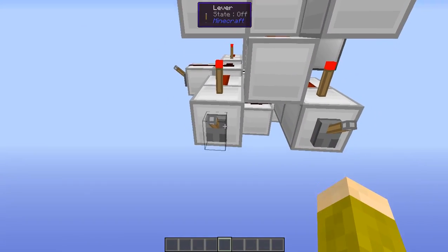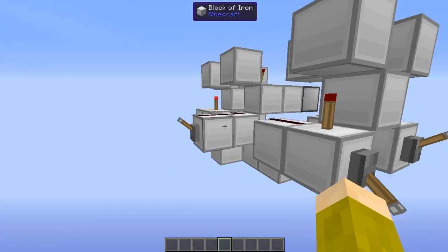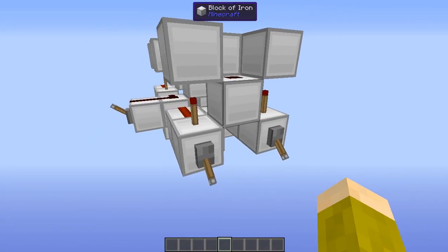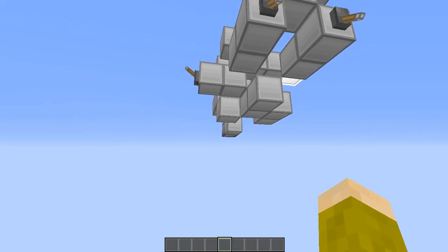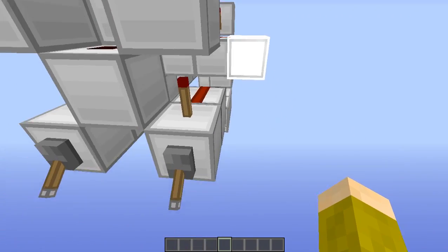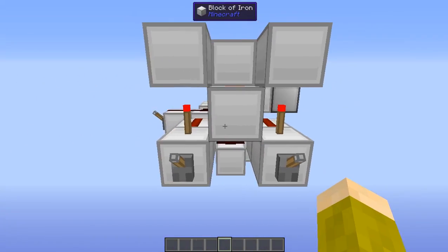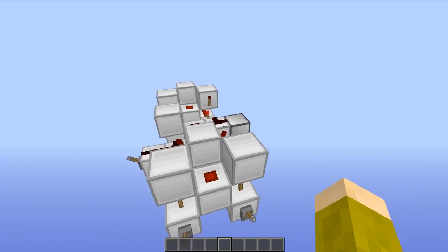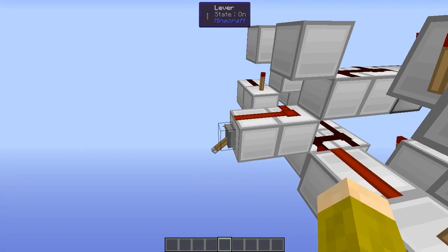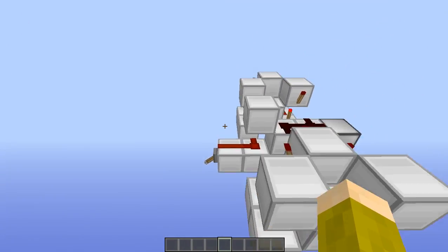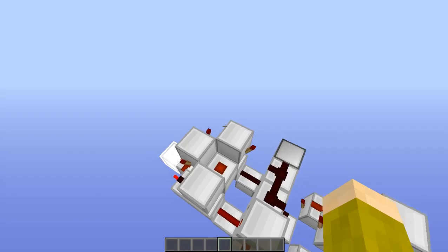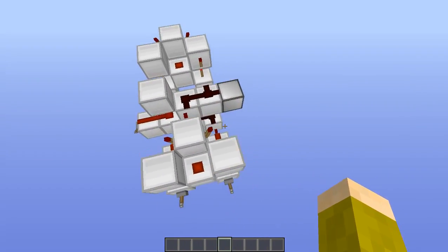So as an example, if I input 1, the output over there is a 1. If I input 1 and 1, then obviously the output is 0, but with a carry of 1. Let's say this carry bit was put into the next adder, because these are tileable this direction. So if I push this lever, it simulates the adder to the left having a carry bit. And this adds 1 to this using the extra XOR gate that was added.